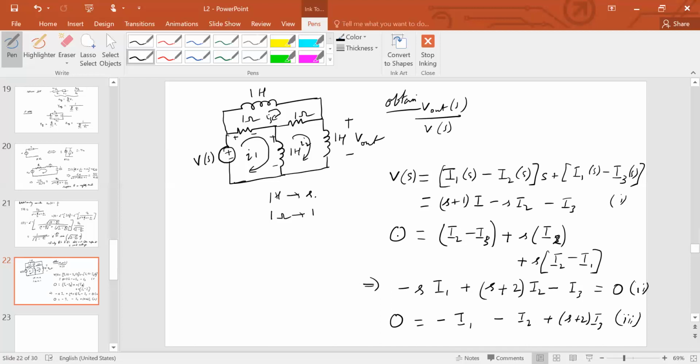So you might have had some voltages here also. In that case, these wouldn't have been zeros. In this case, it turns out that there is only a single voltage source, so it's just appearing in one equation. On the right hand side, you're going to balance out the voltage drops across the elements. So a straightforward way to see this is the loop variable corresponding to that loop will have as its coefficient the sum of all the impedances in series in that loop. Okay, so for example, in this loop it is S plus 1.